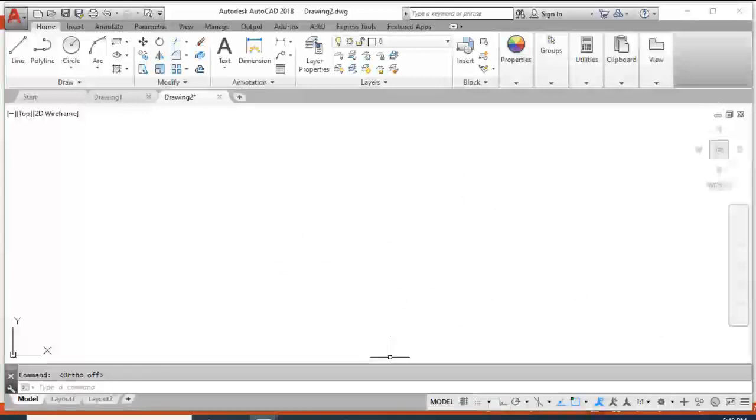You disable it. Then let's come to polar tracking. When you place your mouse on any tool, the name is going to appear after maybe 1 or 2 seconds. Okay? When you enable polar tracking, you can make drawing at any angle you want. So it's tracking the angle. Can you see? That is the essence of polar tracking.